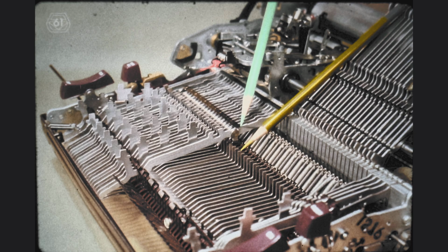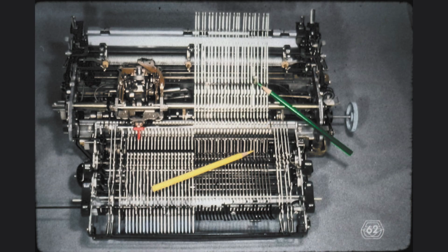Yellow pencil. The lug indicated by the green pencil is the repeat lug used for the underscore keylever. When the underscore key is depressed all the way down into its repeat position, the lug indicated by the green pencil does not allow the interposer restoring spring, yellow pencil, to bring the interposer back up. The repeat lug, by preventing the upward motion of the interposer, also prevents the disengagement, or the restoring, of the cycle clutch.